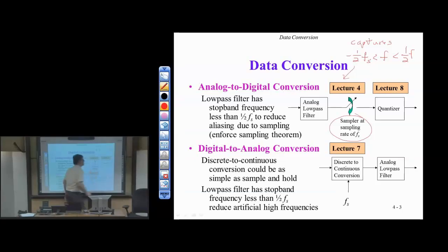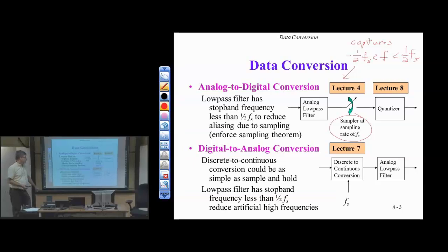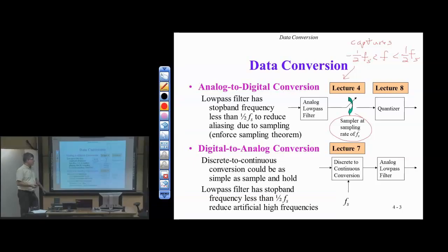This is going to give us a periodic spectrum after sampling. Now, one of these frequencies has to be included to make it periodic. So really, you have to include either half the sampling rate or minus half to make that periodicity work out. Any frequencies above half the sampling rate, and the negative counterparts, which means frequencies less than minus half the sampling rate, will alias. So in practice, we'll always have aliasing because of noise or lots of reasons. There's always something above half the sampling rate in terms of energy content.